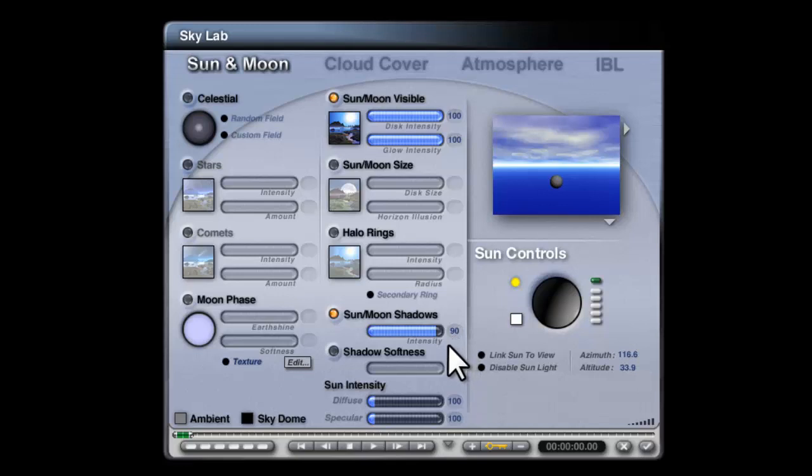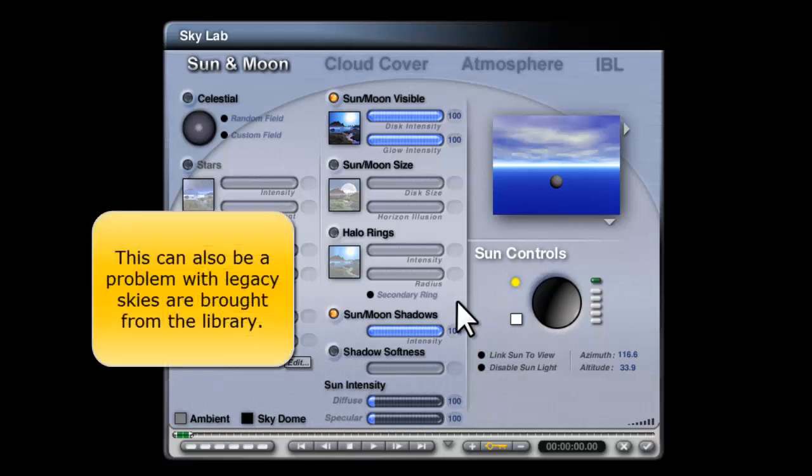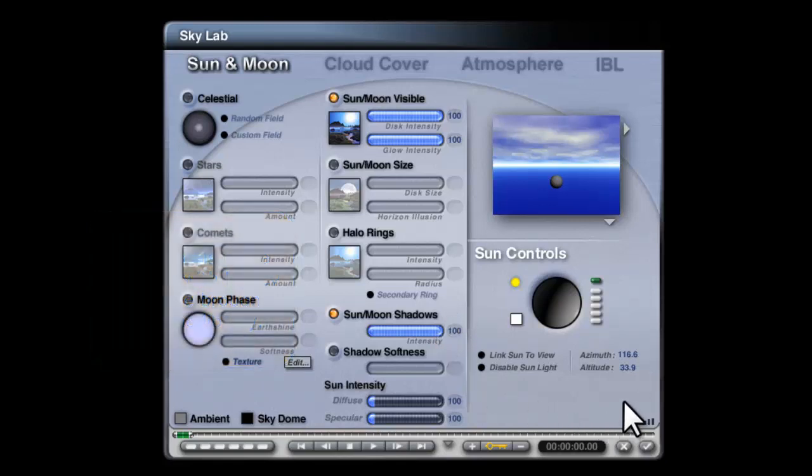So it's spoiling your render by using this old-fashioned way of generating an ambience effect. So if you reset your sky, make sure that the intensity is turned up to 100, and then you'll be able to get fully black shadows. And it also means that when you set your lights up for more sophisticated lighting, they'll work properly, and you won't have this problem where you've not got full contrast because some of the light's getting through. And just remember, this is the global control.